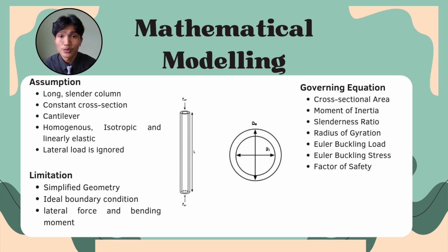As shown by the still images, we model the turbine tower as a vertical, central cylindrical column fixed at the base and free at the top, which is essentially a cantilever. We apply Euler buckling theory to predict the tower's stability when subjected to axial compressive force, ignoring the lateral wind effect for this simplified case.